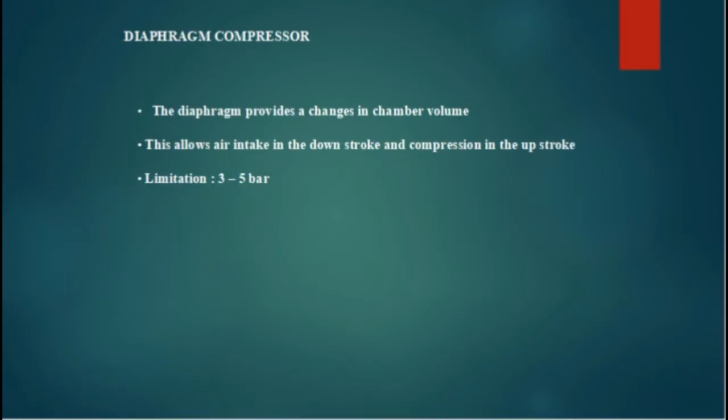Diaphragm compressor. The diaphragm provides a change in chamber volume. This allows an intake in the downstroke and compression in the upstroke. The limitation for a diaphragm compressor is between 3 and 5 bar.